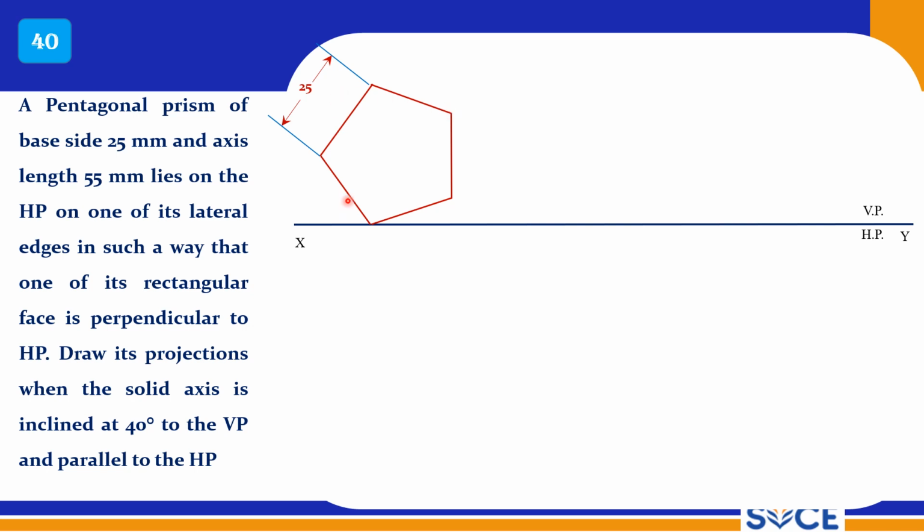So in this case, students, please listen. First draw the pentagon, right, in such a way that this edge is on the right side, right? First complete this pentagon, right? Now draw the XY reference line by touching this point, right? You come in reverse order so that it will be very easy, right? Instead of drawing the XY reference line first, if you try to draw the pentagon, you will make some mistake, right? Definitely you may not get the correct pentagon.